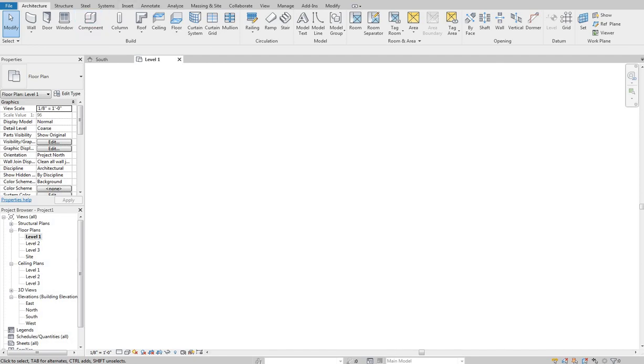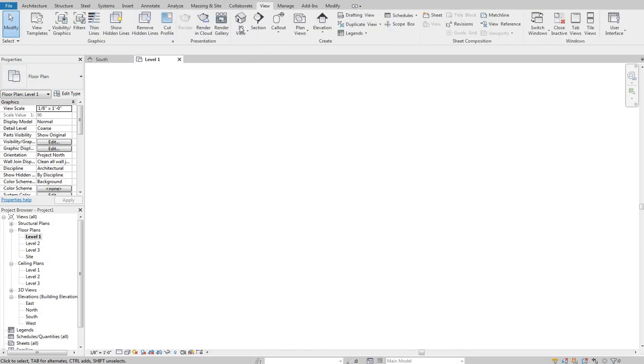As you use various tools, some hotkey items will populate up here that you can use to get to different things without manipulating the ribbon over and over again. So rather than going from the architecture tab to the view tab to find my 3D view, or coming down here to my default 3D view, I can just select the little house up here above. So that's a general user interface overlook at Revit 2019.